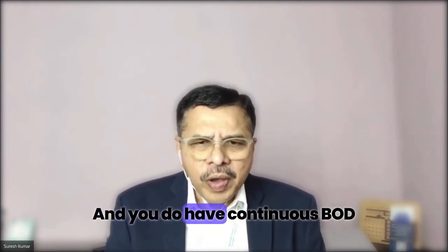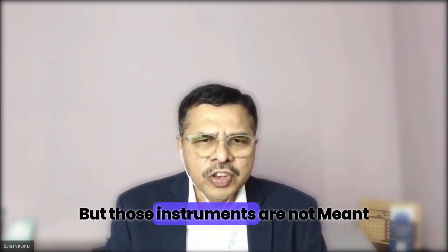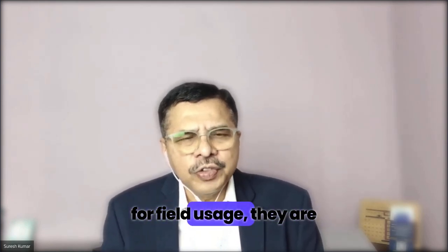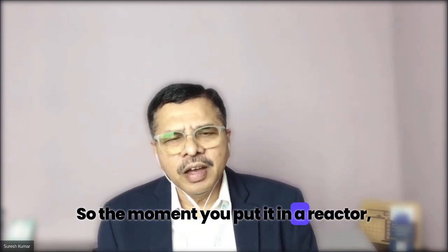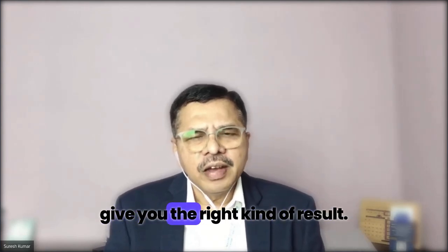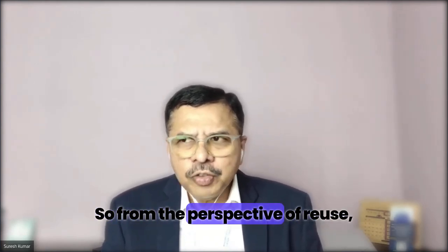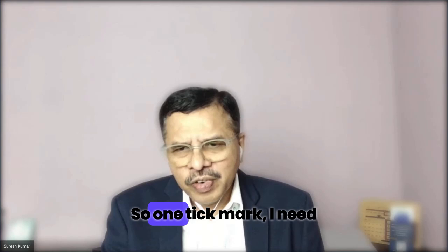And you do have continuous BOD measurement instruments, but those instruments are not meant for field usage. They are meant more for laboratory usage. So the moment you put it in a reactor, your treated water tank, it may not give you the right kind of result.